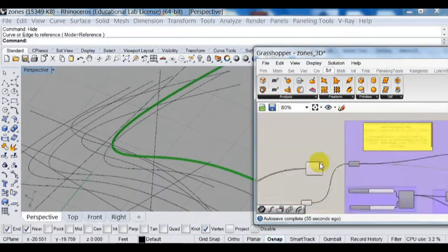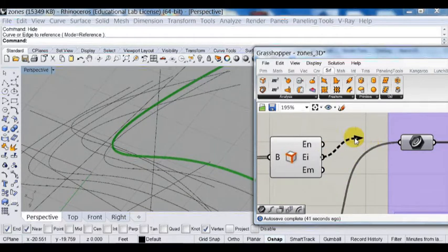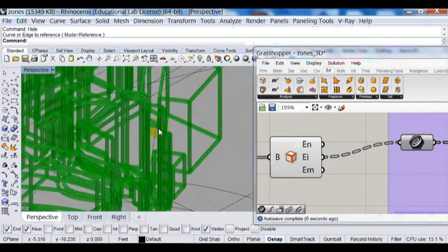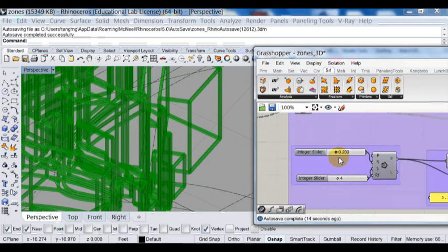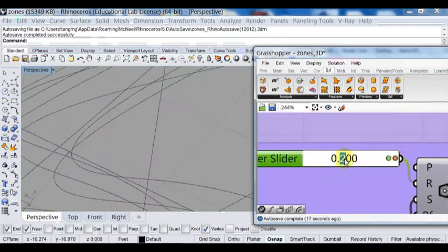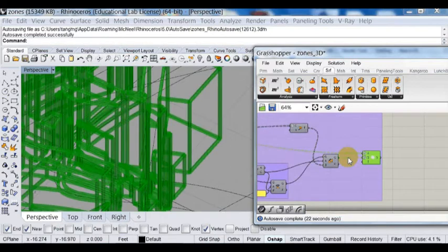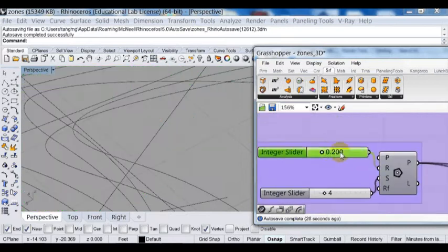So if this works, I can just replace this single line with 612 edges. So you see every single edge is being converted into a super extrude. And you could definitely control it, for example, if I want the thickness to be a little bit bigger, I can give this 0.4, the radius for the square. Then you see the result. It's getting fat. I can make it even bigger. Oh, I think I didn't accept. So just accept.